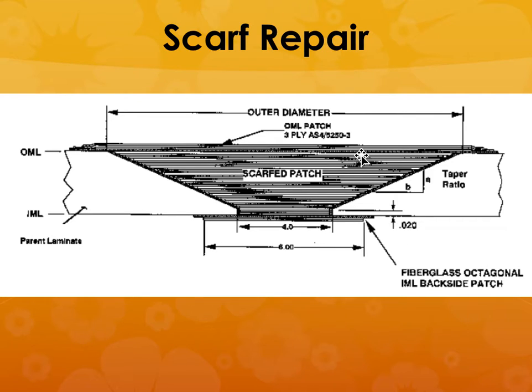So this would be the schematic for a scarf repair. So here the scarf area is straight, so that this material that you are adding in matches well, and the profile is well matching the original structure.